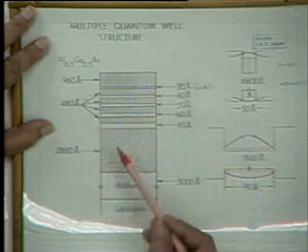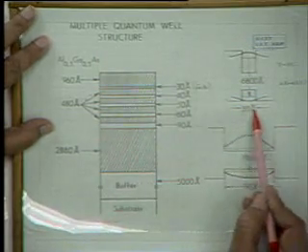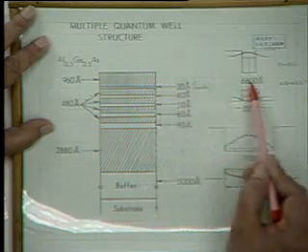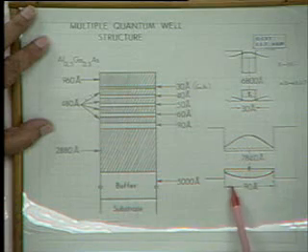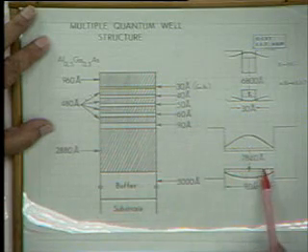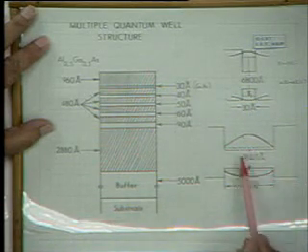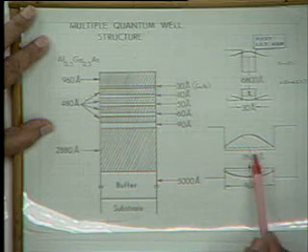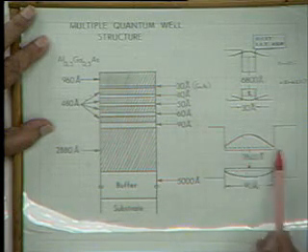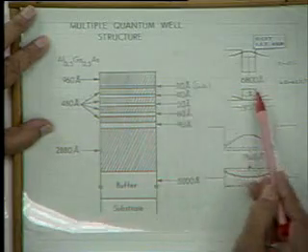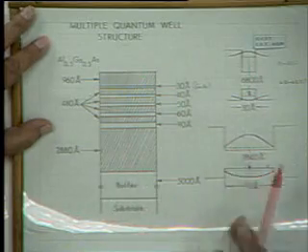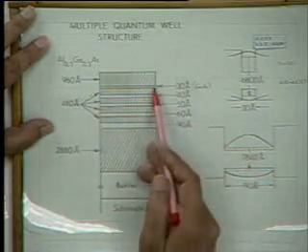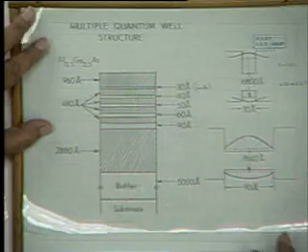by laser light, from the 30 angstrom well you will get emission at 6,800 angstroms. From the 90 angstrom well you will get emission at 7,840. So this energy immediately tells you what the well width is. And as expected, as you have a narrower well, the wavelength goes to shorter values. So with the same material, just by varying the well width, you can get devices working at different wavelengths.